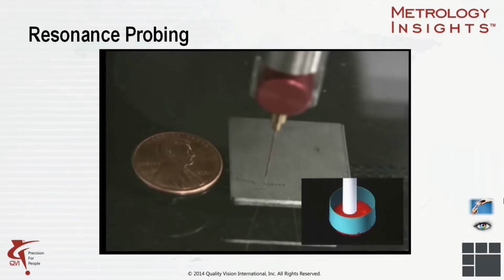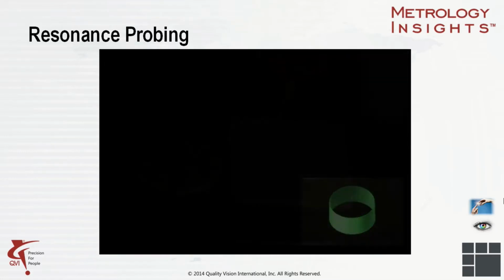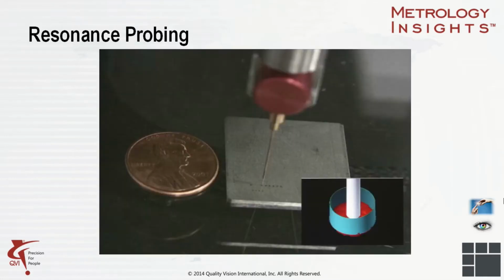The feather probe is constantly resonating at a high frequency, and as soon as it gets close to a part or actually touches it, the frequency changes. This technology is ideal for measuring parts that are flexible and can't be accurately measured using conventional probing force. The feather probe shown in this video requires only 5 milligrams of force to trigger. So little, it can probe a feather without deflecting it, or probe the surface of water without creating a wake.